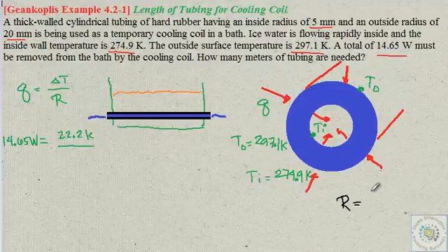In this case, that's delta R. What else? It's also inversely proportional to the conductivity. The higher the conductivity, the smaller the resistance, and also with the area. The bigger the area where heat could flow, the smaller the resistance this will offer.